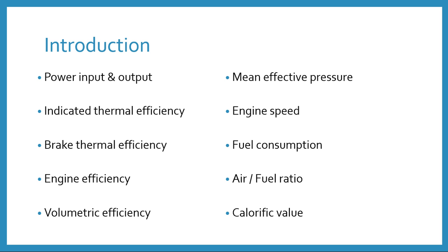We can study the power input and power output, and how to calculate the input power and the output power of the engine. Then we can understand the various types of engine efficiency, such as indicated thermal efficiency, brake thermal efficiency, mechanical efficiency, and volumetric efficiency. And we already know that some pressure is required to complete the principle of the IC engine, so we need to calculate the mean effective pressure.